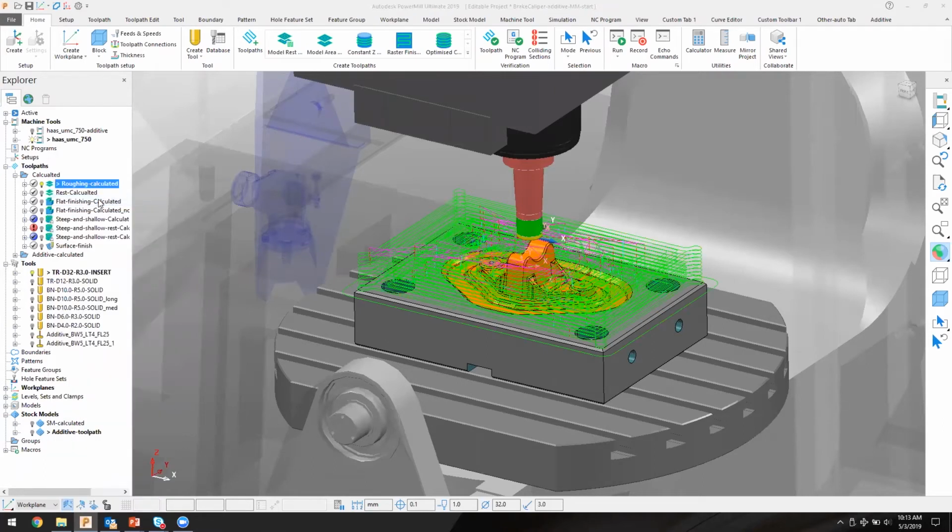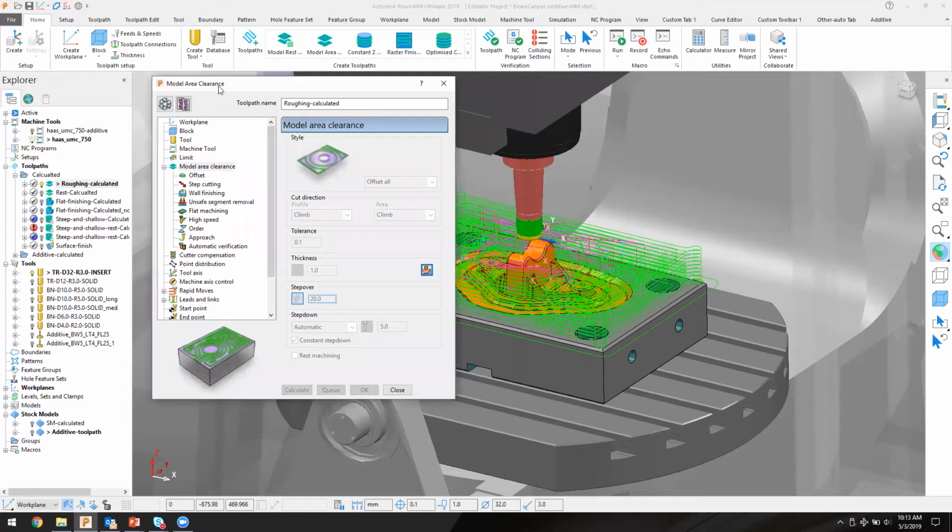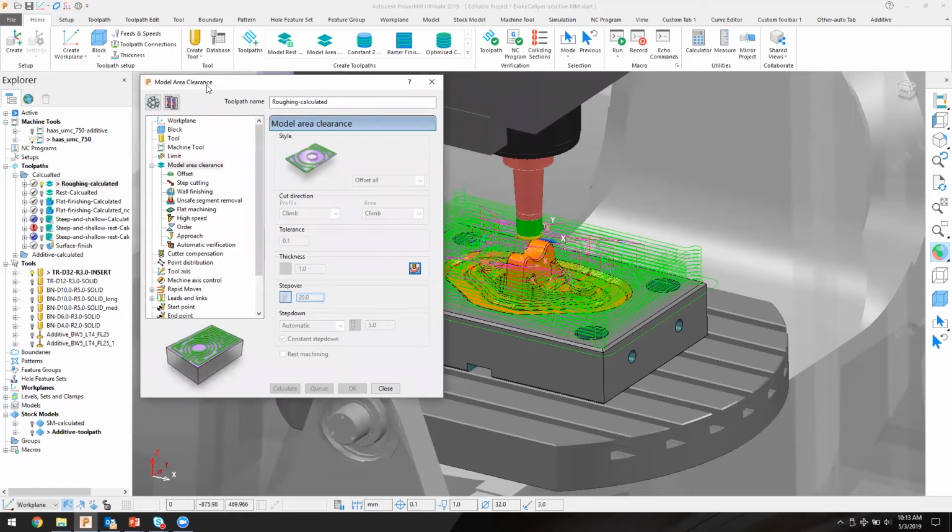Once a toolpath is created, we will see the settings form that pops up. Most of the toolpaths that you will see today, just one is going to be different, all contain the same overview settings look for each toolpath. And it again has a very linear workflow. You work from the top. What is the Z direction that you're moving? What's the work plane that you're using? In this case, we're doing subtractive, so what's our machinable area? The tool that we're using, any limits, and then the actual settings of the toolpath, such as how much material we will leave and the step over of the tool.